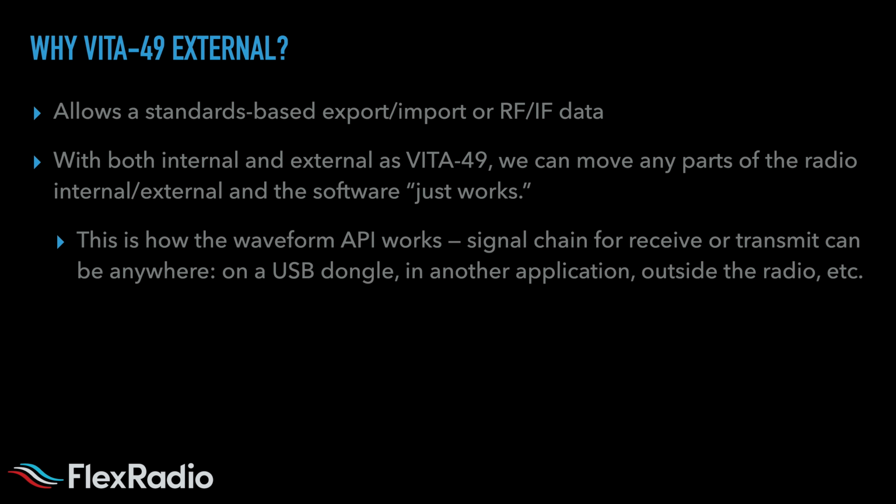Another one is D-Star. Because D-Star uses a proprietary codec, we utilize a device called ThumbDV, which plugs into the USB port of the radio, but then that uses the Waveform API to do D-Star transmit and receive through the radio.